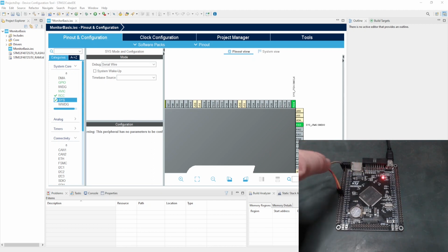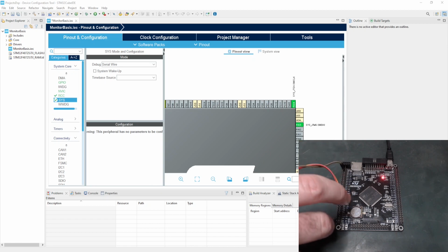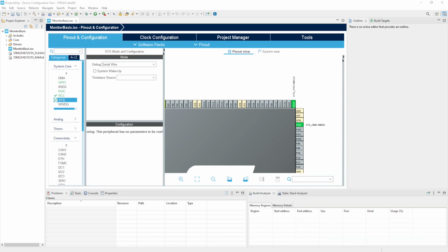So I don't need to connect the 3.3 volts line of our ST-Link to the development board. Only the GND as a reference and the signal pins, clock and IO, SWDIO and SW clock. So they are very important in order to establish a connection to transfer our projects to the microcontroller. So that's it for the first moment here.